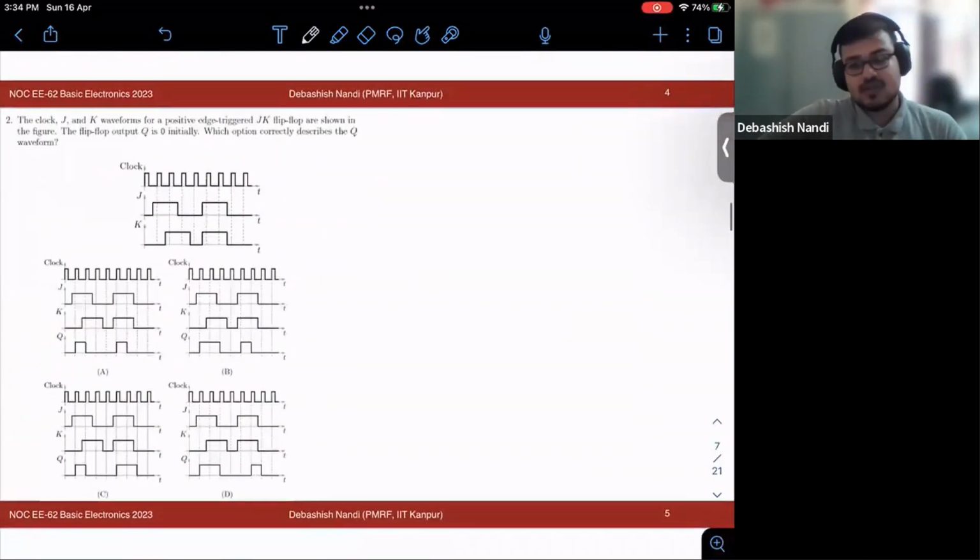See, latch was fine, right? With latch we can store one memory, but the issue with latches is that we need to change the inputs to get our output states changed. Many times it is not possible for us to change the inputs once they are supplied to the pins of an IC. So we need some other controlling handle to change it.